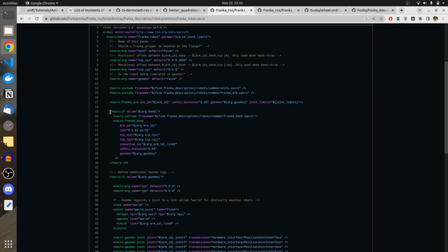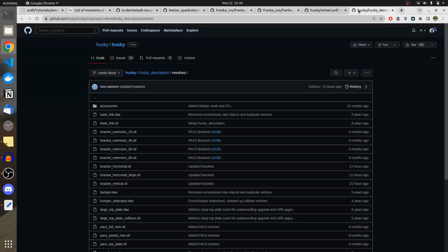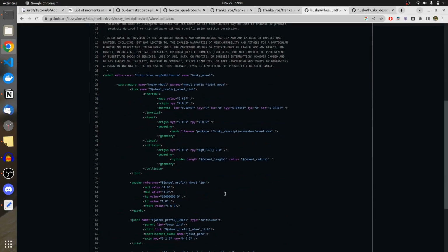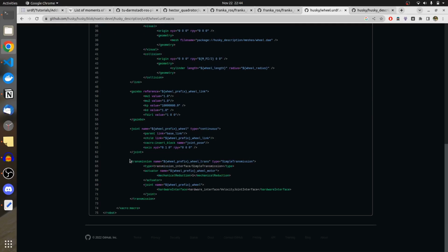New things are also there, like if conditions applied that we have not done, but you can go through it, you can understand a lot of things. You don't need to look into the thing that has nothing to do with Xacro. It's basically a plugin. That's why I wanted you to take a look into the code of commercial robots and understand how their URDF has been written. These transmissions have to do with ROS control, nothing to do with Xacros. Okay, we'll understand it in the upcoming lectures.